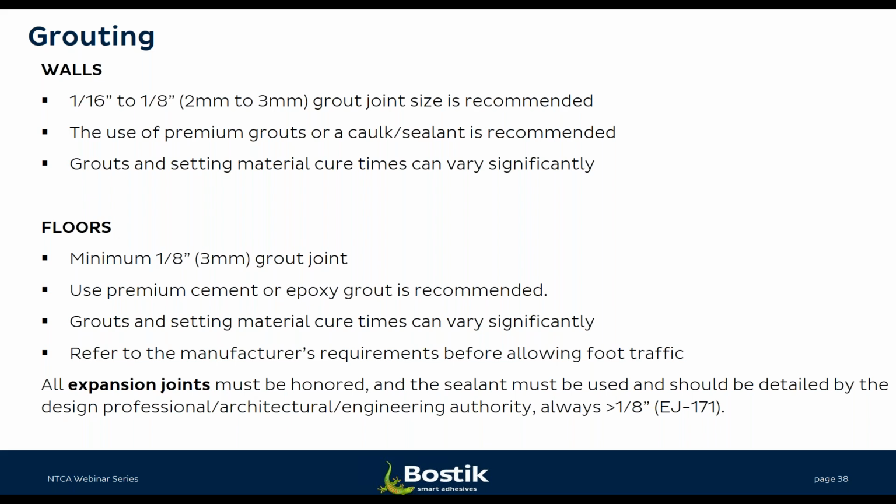We see in floor applications the use of epoxy grouts, whereas in the walls we see urethanes and cements, or we even see some caulk and sealants based products used on walls. So silicone sealants are often one of the products turned to because of the wide assortment of colors available in silicone.